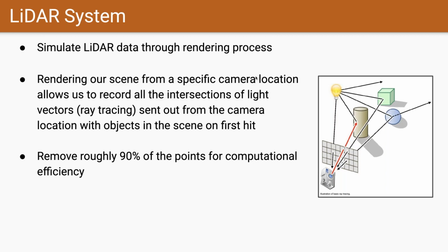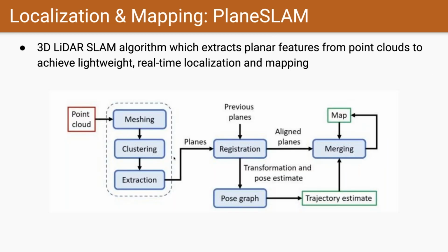But Lidar gives us a flexibility because it allows us, if I have 2 or multiple drones, I can put all the point cloud together, then do a method like DBSCAN to construct different parts of the object, and then combine those 3D scenes. And we basically remove roughly 90% of the point clouds for efficiency purposes so that our Lidar system can be really fast.